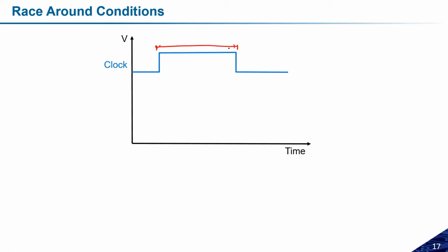Okay, and we know that in the RS flip-flop, if the clock is activated, I'm considering the positive level triggered one. This means the logic of the clock is high and the duration is this much. For positive level triggered, the flip-flop will be triggered if the level is high, like the clock pulse is high.